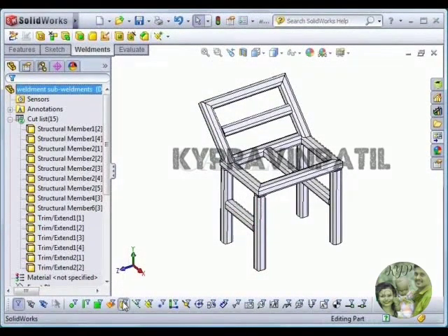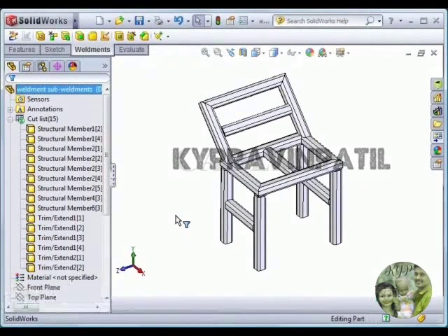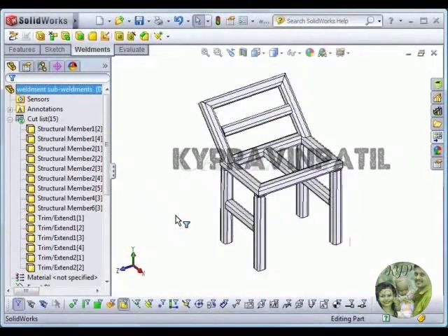I want to point out that when using selection filters, I tend to use the F5 key on my keyboard. This is a Solidworks shortcut, allowing you to turn the filter toolbar on and off with a simple push of a button. Now you can make your selection directly from the graphics area.